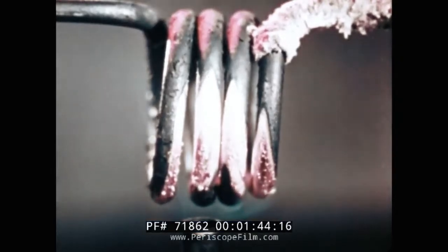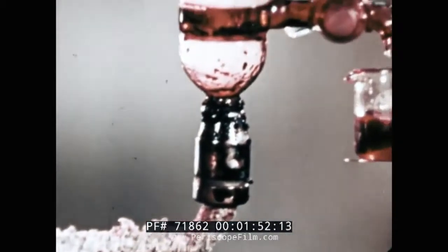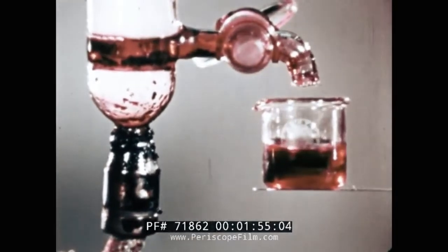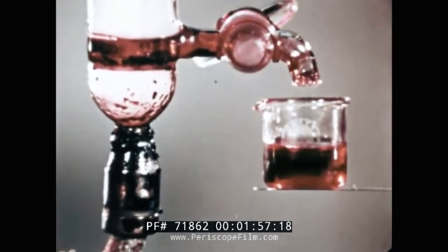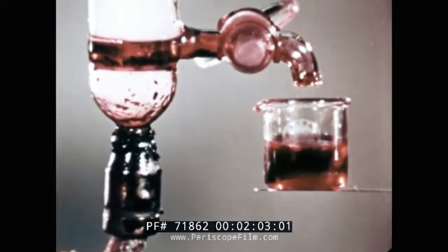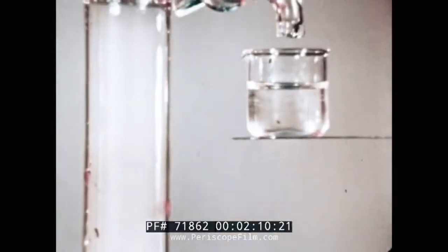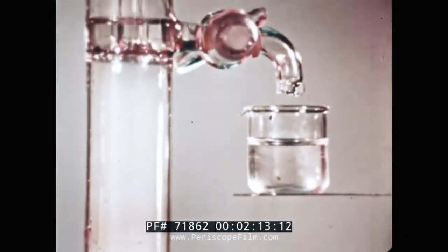Here's one way to do it. Heat the mixture inside the tube so that both liquids are vaporized, and feed the mixed vapors to a column where they are cooled. Near the bottom, the vapors are cooled to just below the boiling point of the dark liquid. So it condenses here and can be drawn off. But it's far too hot for the vapor of the clear liquid to condense. So it rises until it too is cooled sufficiently to condense. At the top of the column, clear liquid is collected, and at the bottom, dark liquid.